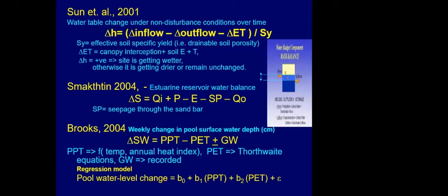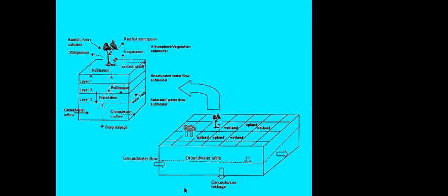So these are some of the literature. See how layers should be taken when you are making hydrological studies in a wetland. One needs to consider even the root system. When I did a study, every 30 centimeters was one layer, 30 to 50 centimeters was layer 2, then layer 3. That level of investigation is required.